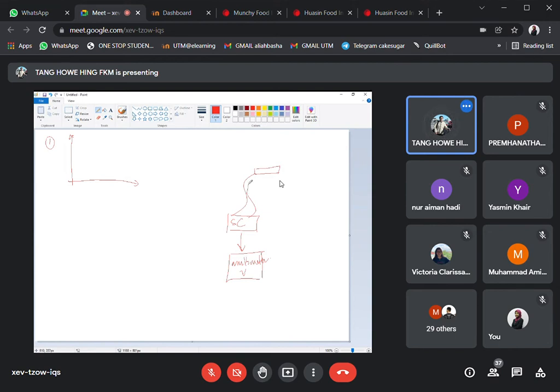So regarding the calibrations, we want to find a relationship which relates this voltage, and here that is the weight. Right, so the weight will be applied at this load cell. Because you already have the signal conditioning and it is connected to the multimeter, you can easily make certain measurements.